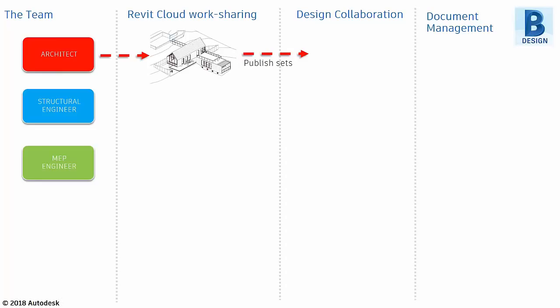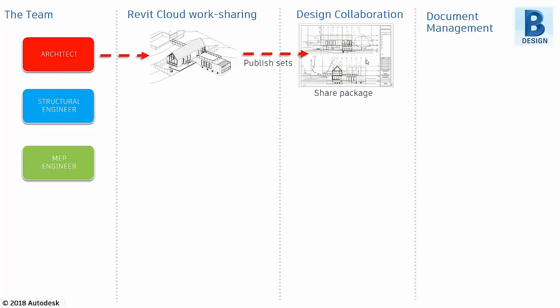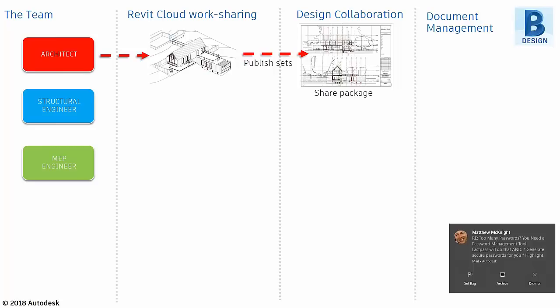With the design collaboration component, you publish your sets from Revit. So whenever you come to publish information, you can create a number of sets for your sheets or your model views. And this can be reviewed inside of design collaboration as a package.